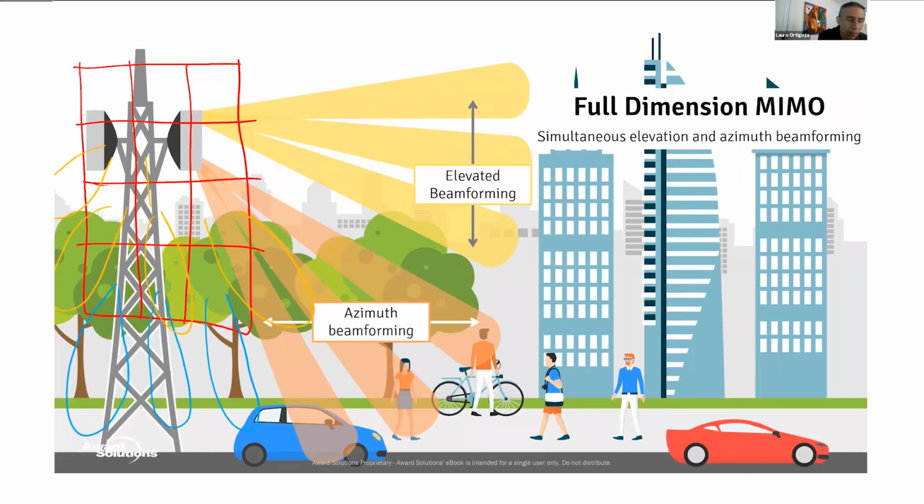I told you that in order to create beamforming, you need antenna elements. So in this case, assume that we have the following antenna elements. I'm going to draw them. This is the antenna element, the yellow one. We have 4 antenna elements for my first subarray, and these yellow ones, amigos, are connected to, let's say, port number 2.